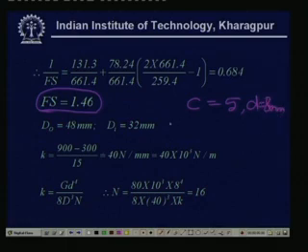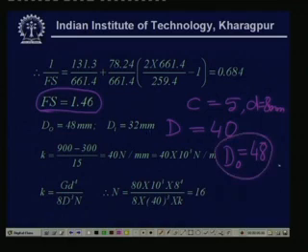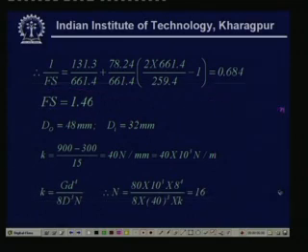So, the capital D comes out to be 40 and the outer diameter comes out to be 48. Obviously, this is well within the prescribed limit and we can select these dimensions. Once we select these dimensions, from the standard formula we learned earlier, D0 comes out to be 48 and Di 32 mm.